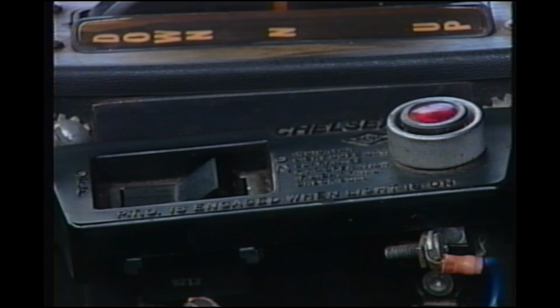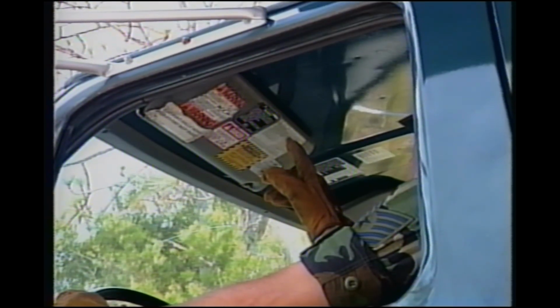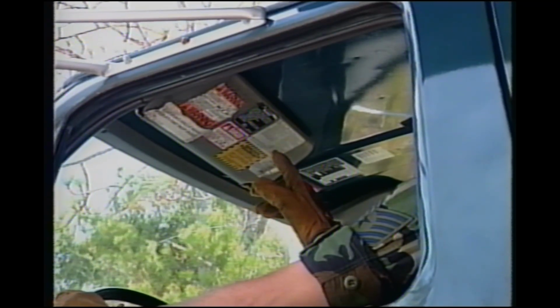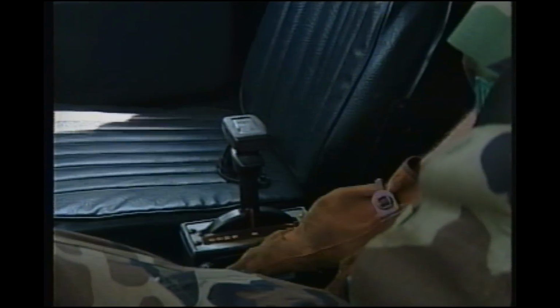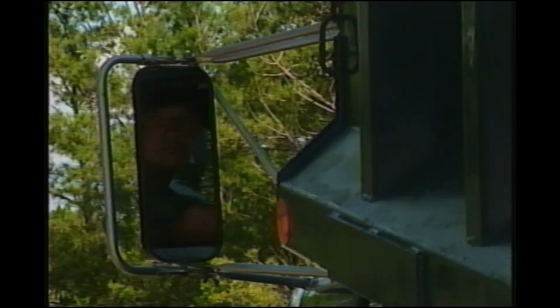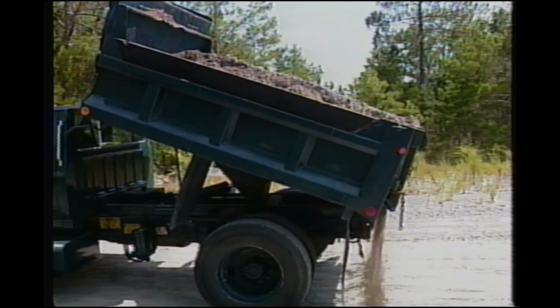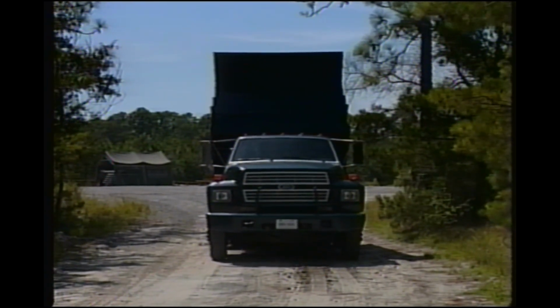Our next step is to engage the PTO. Each vehicle manufacturer has a slightly different procedure for accomplishing this task. Read their instruction decals or the operator's manual. It'll make this step easier and reduce wear and tear on the dump truck. Watch the outside mirror and raise the bed until material starts to flow onto the ground. Check the area in front of the truck and pull forward.